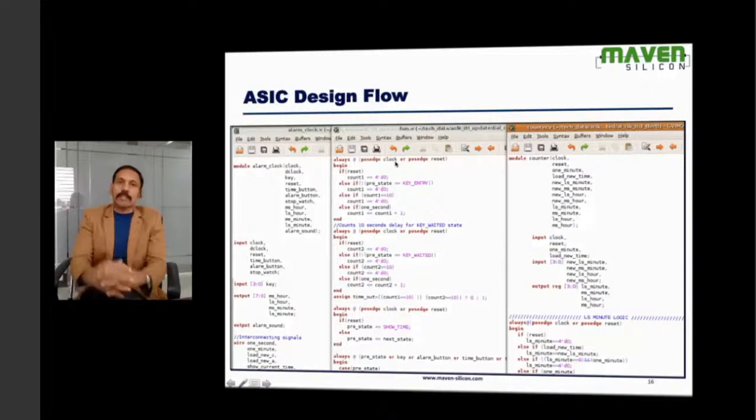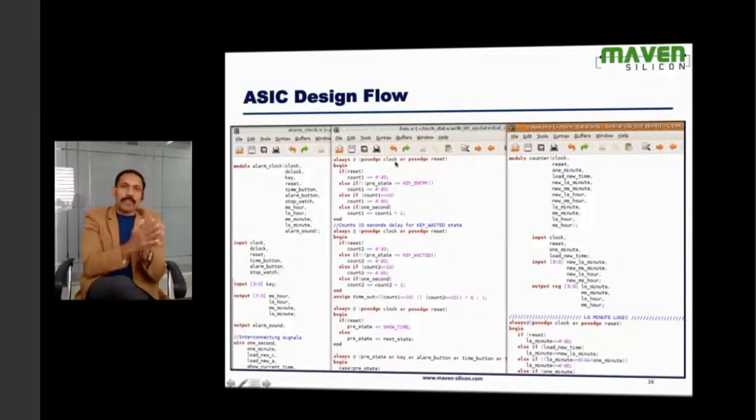The other thing is coding style. You want to implement a sequential logic, something like flip-flop, so you need to use posedge clock in the sensitivity list. Or you want to implement multiplexer, it should be a parallel logic, so you have to use case. Or you want to use prioritized logic, something like priority encoder, then you may want to consider if-else. So different logics demand different kinds of coding style. You need to understand both synthesizable subset and coding style.